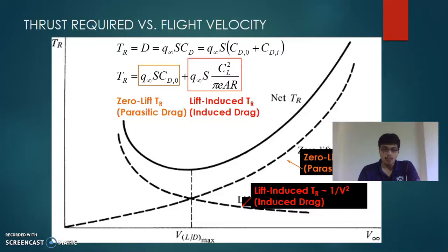Now, once looking at this, we also now know the lift induced thrust, which computes. So what we are doing in this graph is simply resolving the thrust component into two parts. One, we say thrust because of drag, which is simply a function of the drag profile and induced drag profile, and thrust because of the lift. What does that mean? As you keep increasing velocity, the drag will ensure thrust goes up. But as you keep increasing velocity, the lift will keep bringing it down. And hence, when the drag wins, the thrust requirement wins. That's the simple explanation.